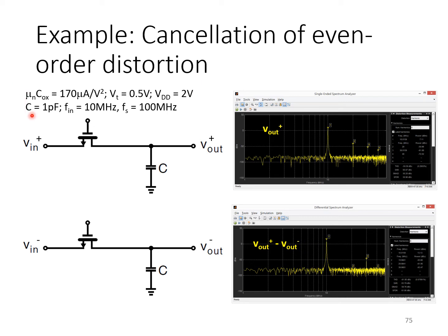The circuit's nonlinear because the transistors in triode are not perfectly linear. With any VDS appearing across them, then we're going to exercise the transistors' nonlinearities. And a VDS will arise across them, especially at higher frequencies, because the low-pass nature of the RC network formed here means that the output amplitude will be a little bit less than the input amplitude at high frequencies.